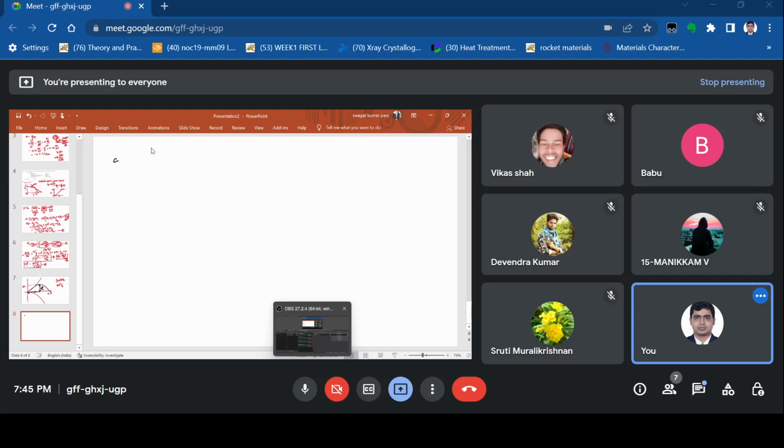So undercooling is basically, this is our melting point. Delta T 100 Kelvin means this is our delta T, this is our 900 Kelvin. If we assume this is 1000, then this is 900. So delta T is given, melting point 1356 Kelvin, that is given.